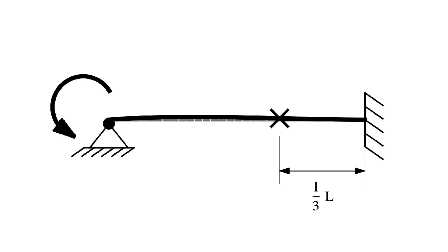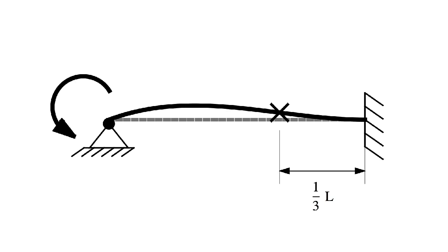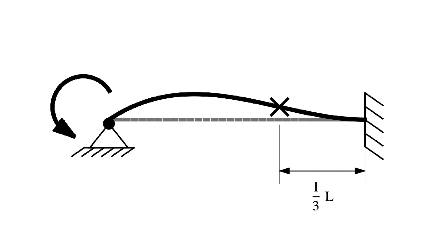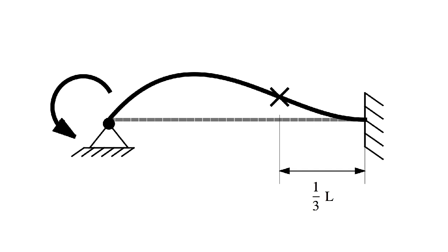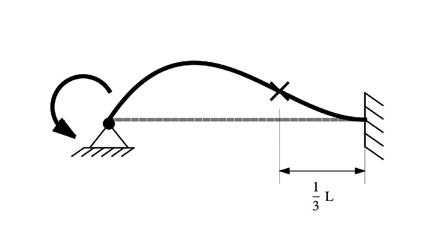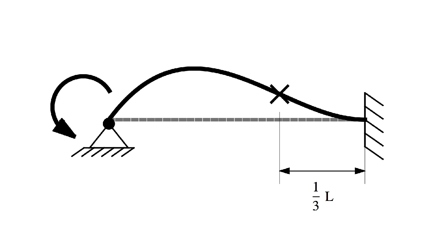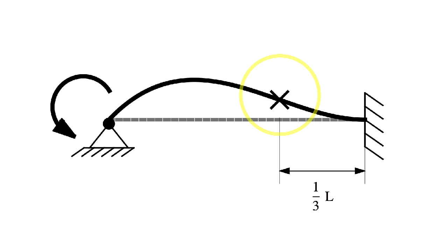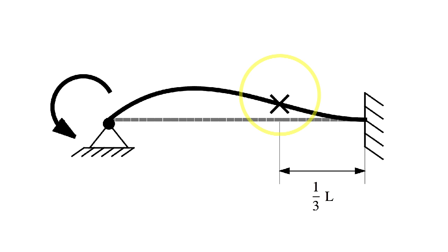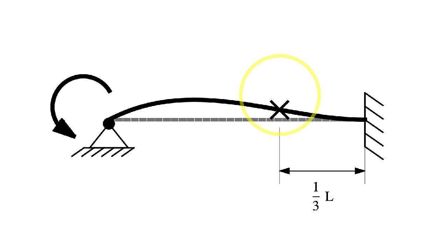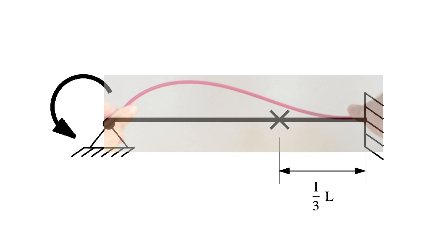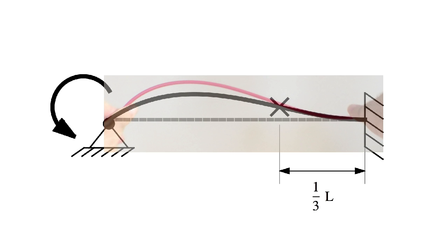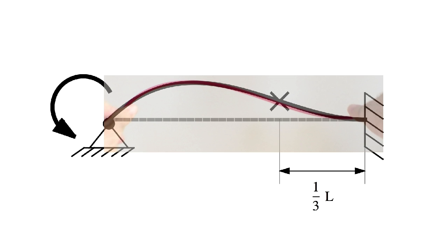The shape that we now get is different from the simply supported or hinge-hinge case. This shape has both negative and positive curvature. At some point between negative and positive, this curvature, and therefore also the bending moment, must be zero, and we call that point the inflection point. An inflection point is where the bending moment, curvature, and bending stresses are all zero. It is the eye of the bending stress storm. Now, we again compare the theoretical deformation with the deformation of the straw, and again we get a good match.